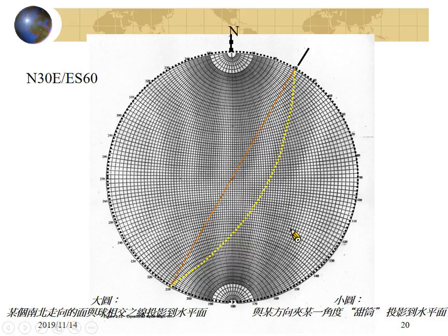Okay? What is the normal vector? The normal vector will be 90 degrees to the dip direction, perpendicular to each other. This will be the dip direction, and this will be the normal vector. So, where is the pole or the normal vector of the plane? It will be roughly here. And counting 90 degrees. So how to count the 90 degrees? You need help from the great circle, right? Incline angle 90 degrees.